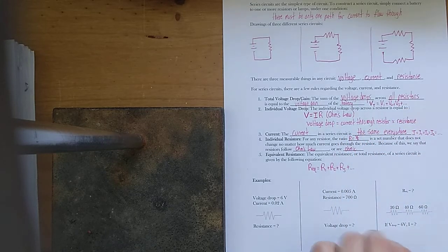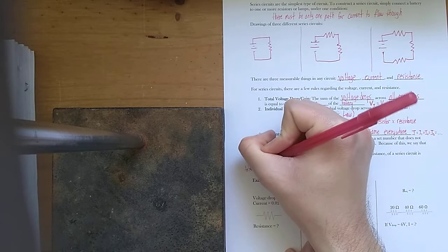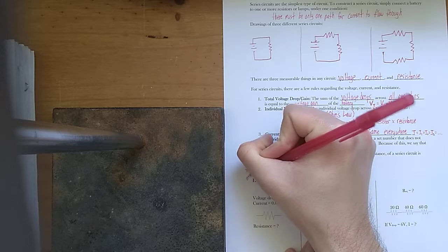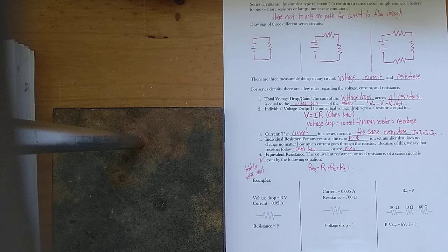Okay. Now what this means, equivalent resistance. Equivalent resistance really means kind of like the total for the entire circuit. You can also find equivalent resistances for parts of a circuit, but because we're going to deal with very simple circuits, equivalent resistance to us means the resistance of the total circuit, the circuit as a whole. In essence, imagine you could combine all these resistances into one big resistor. How much resistance would that resistor have to have to do the exact same thing that these 2 or 3 or 4 or whatever individual resistors do?